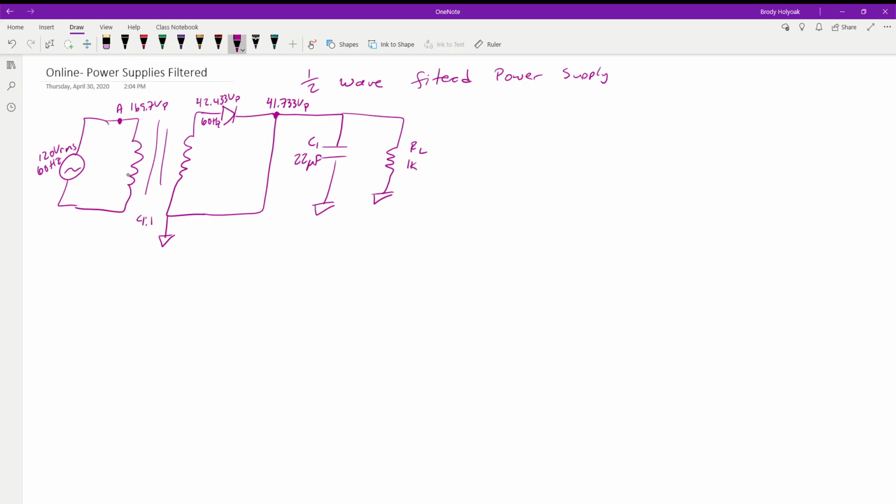So in here, we don't have any resistance. Our tau is pretty much just going to be the resistance of the wire, the resistance of the coil over here in the secondary of the transformer. So our tau time is going to be really, really short, a very small time that it takes to charge. So our capacitor is more or less going to charge instantly.